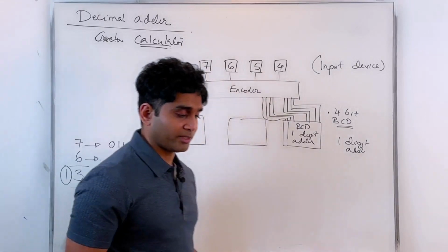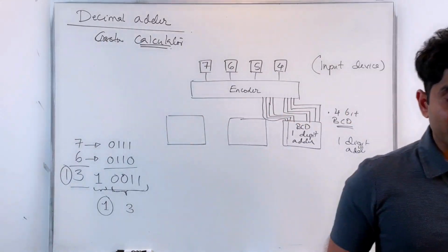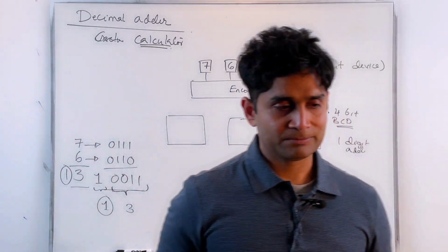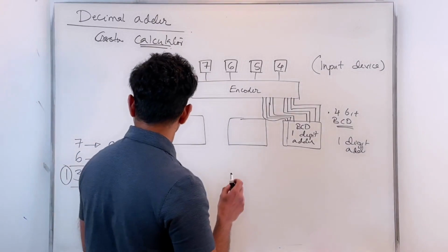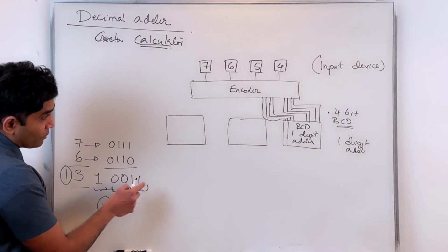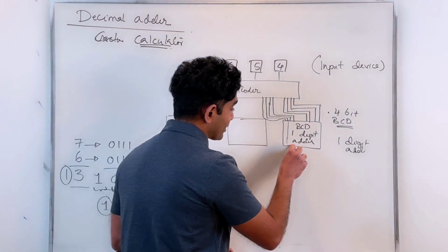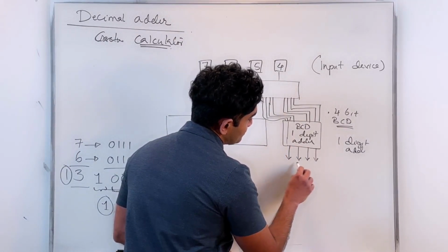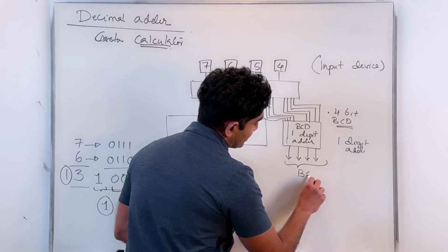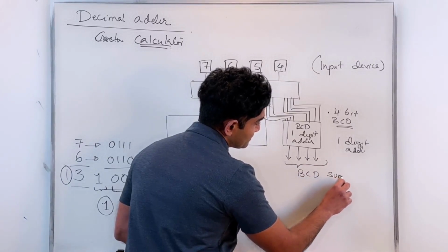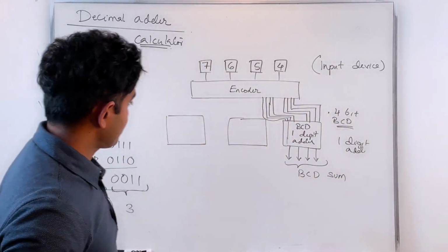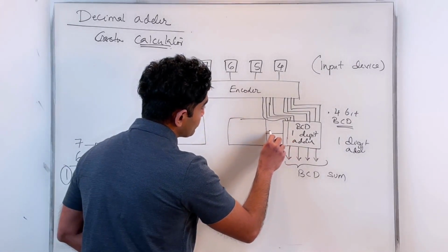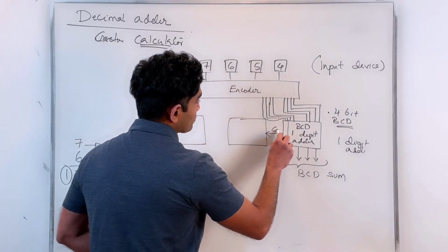When we are working with binary coded decimal values, does that make sense? In other words, I would have 4 outputs, 1, 2, 3, 4, because my sum is also a binary coded decimal value. That's my sum. This is the binary coded decimal sum. And this should also have a carry out, which would be going into the next one, right? Carry out.